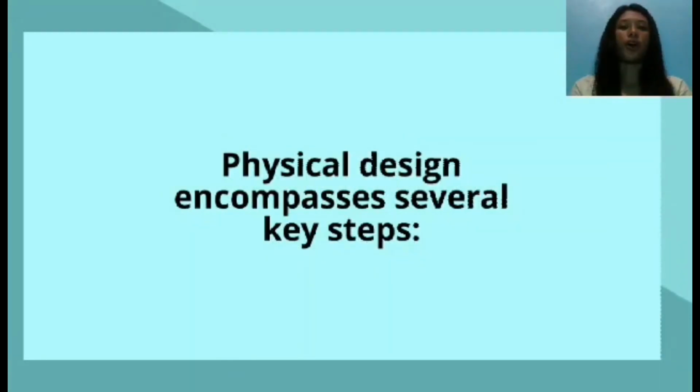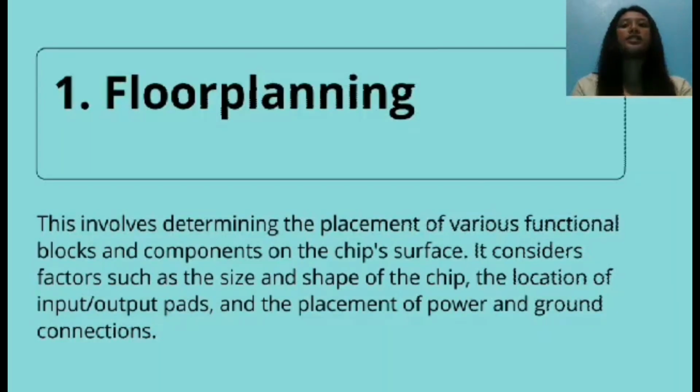Hello, good day everyone. So now we're going to tackle physical design, which encompasses several key steps. First one is floor planning. This involves determining the placement of various functional blocks and components on the chip's surface.